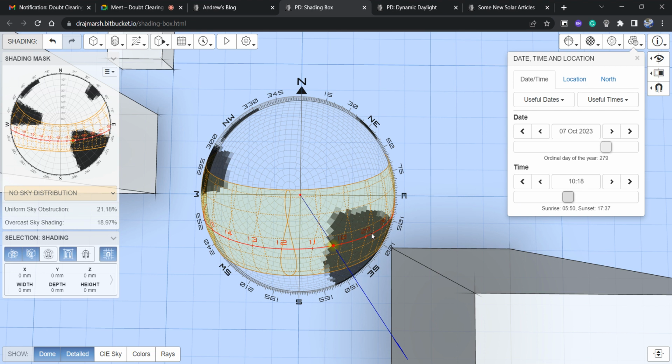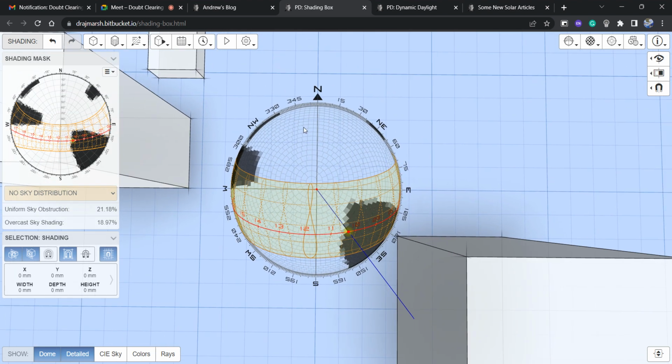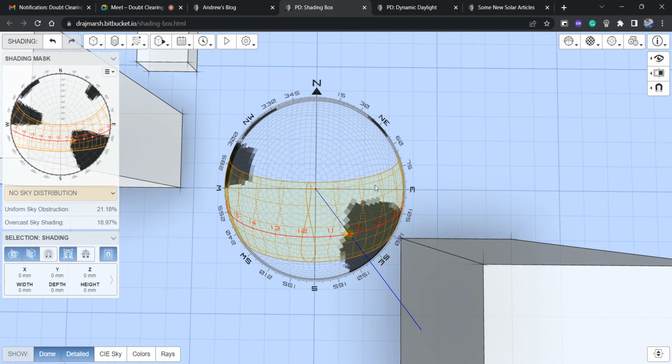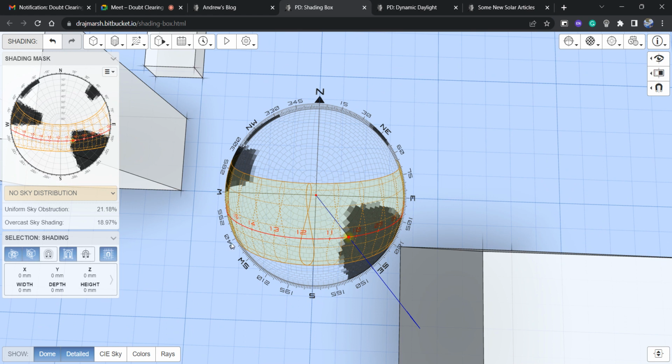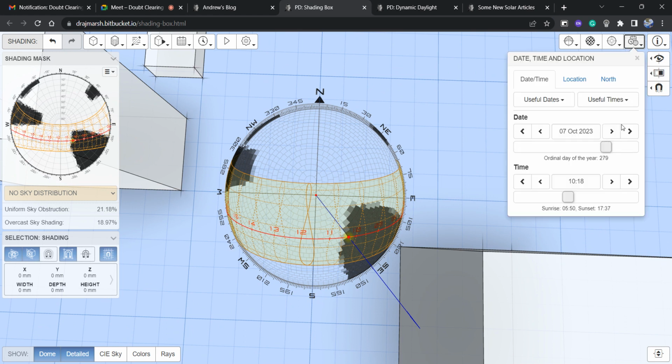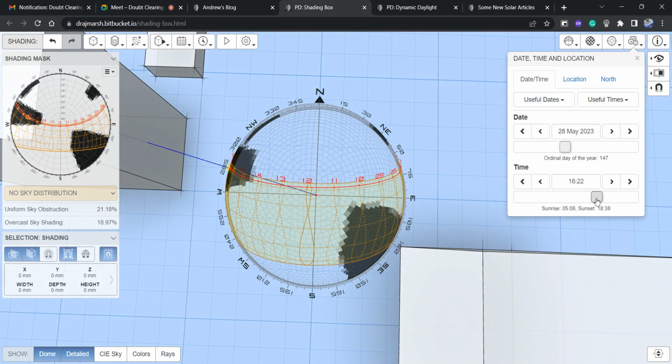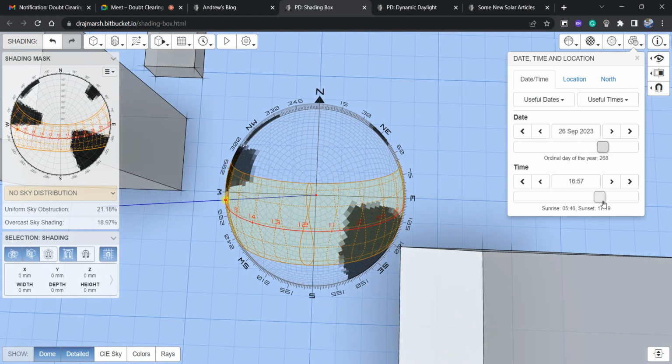So this tool can be used to get an idea that in this time period we don't have direct solar radiation, or that we will get ample solar radiation on this side. If we don't want solar radiation, we can zone particular spaces on that side of the site. On the southwest side, you can see there is radiation mostly throughout the year during the afternoons.